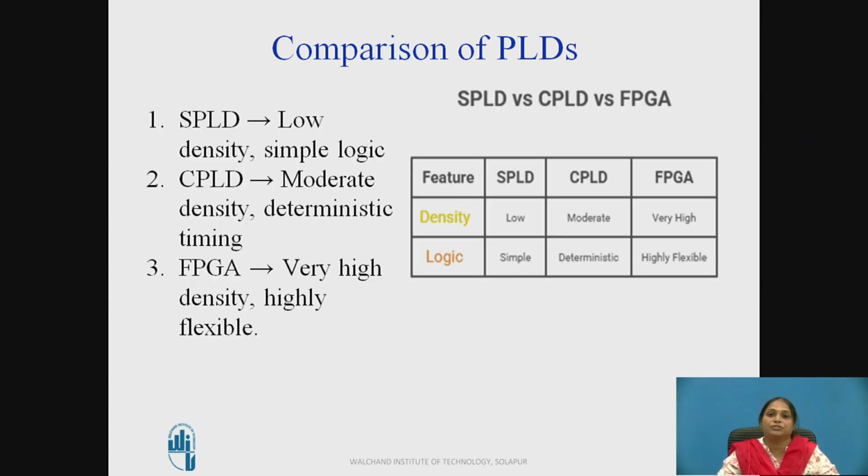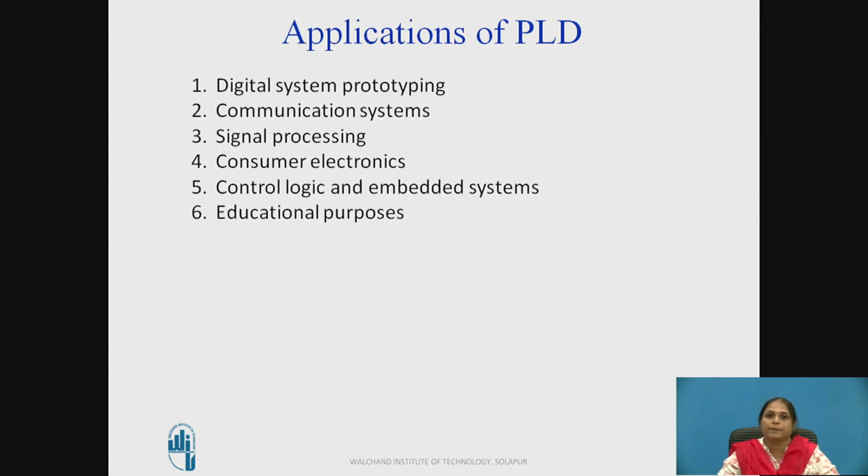The comparison of PLDs can be done as SPLD, CPLD and FPGA. SPLD's density is low, CPLD's density is moderate, and FPGA density is very high compared to CPLD and SPLD. The logic implementation in SPLD is simple, whereas it is deterministic in CPLDs, and it is highly flexible in the FPGA.